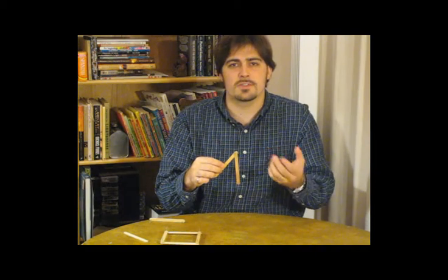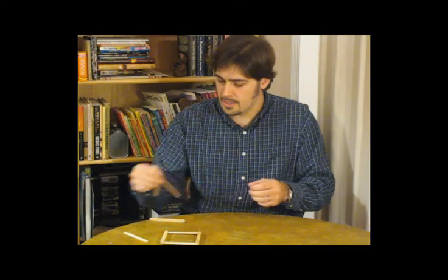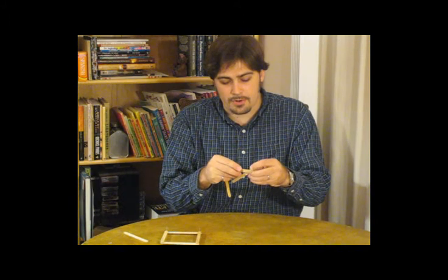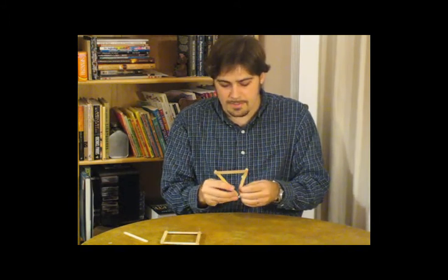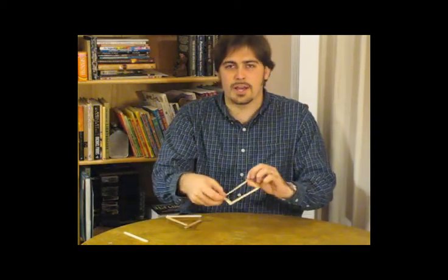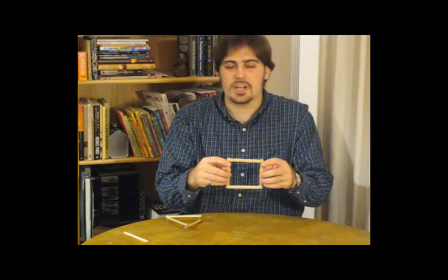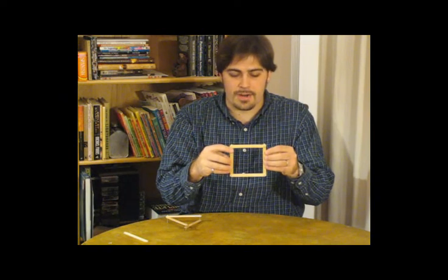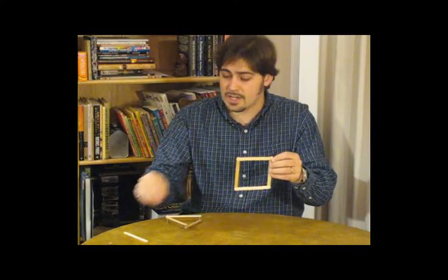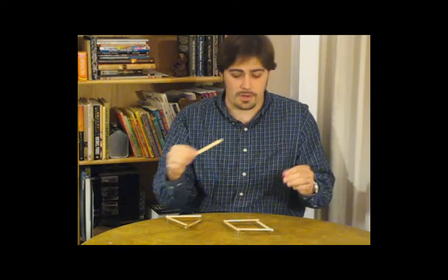So again, the question is, what is it about triangles? Why is it that a triangle makes a strong structure? Well, to answer that question, why don't we take a look at a quadrilateral and then look at a triangle and see how they might be different. So here I have a triangle and here I have a quadrilateral. Now the main question we need to ask ourselves is, how many shapes can we make with the quadrilateral without violating one of the rules that I gave us? Remember, the rules were we can't change the length of the member, and the other rule was that the members can pivot one relative to another.